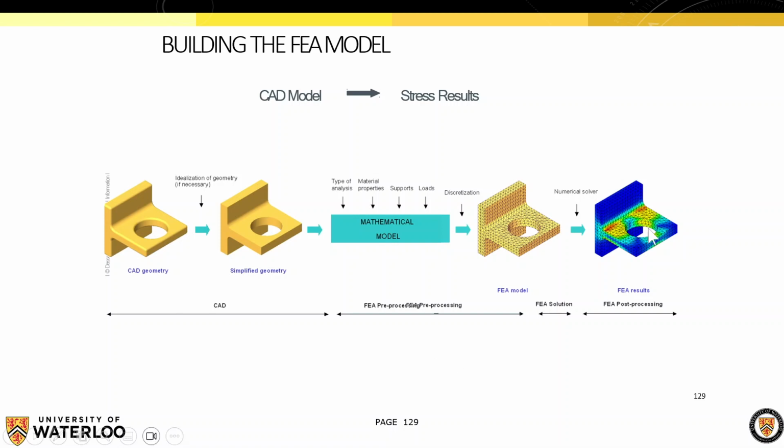The final thing, the fifth ingredient, is your mesh: the type of elements that you're going to use. How many bricks are you going to use to actually compose this geometry? What shape are the bricks? Are they rectangular prisms? Are they tetrahedrons? We'll talk about each of those in a little more detail. And then finally, this is the back end of the software that a lot of people don't see, but I encourage you to develop an appetite to understand it: the numerical solver.